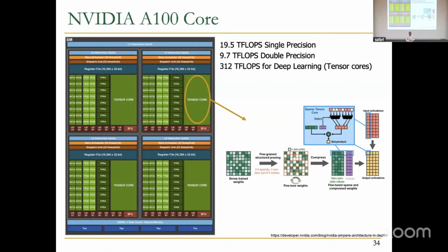What it does is it has a different data type that is actually better for machine learning, and clearly compilers need to take that into account. But they have support for sparsity also. Sparsity means that in machine learning and in a lot of applications, your matrices may have a lot of zero values because some of your weights are all zeros, for example. Multiplying by zero is kind of a waste. We discussed this a long time ago when we talked about scheduling instructions. Multiplying by zero is easy, so why do you actually do the full multiply? Why are you taking 8 cycles to do a multiply?